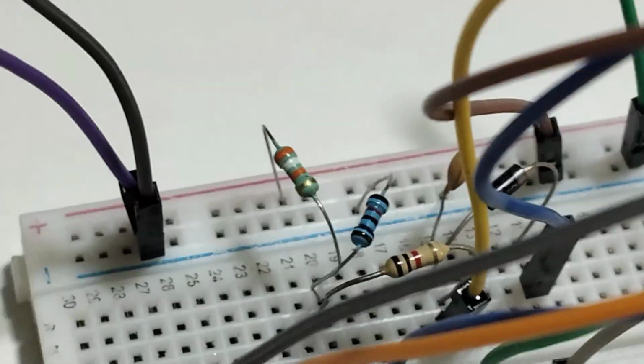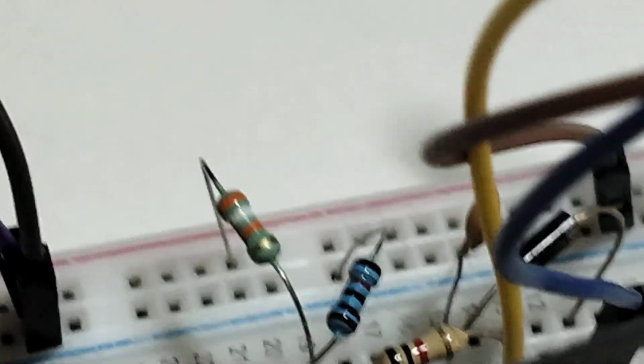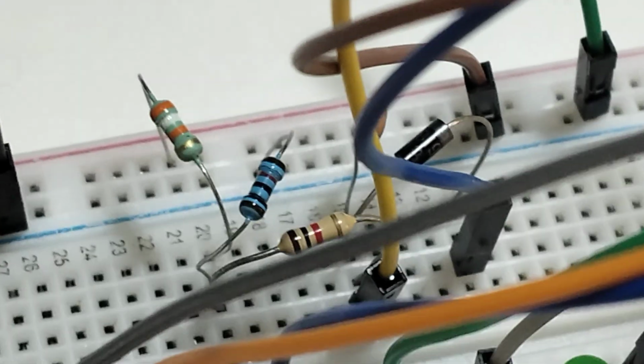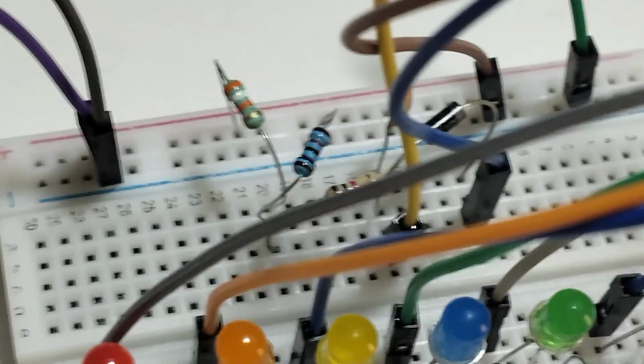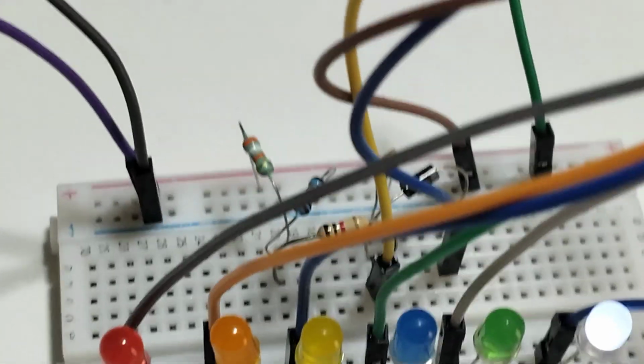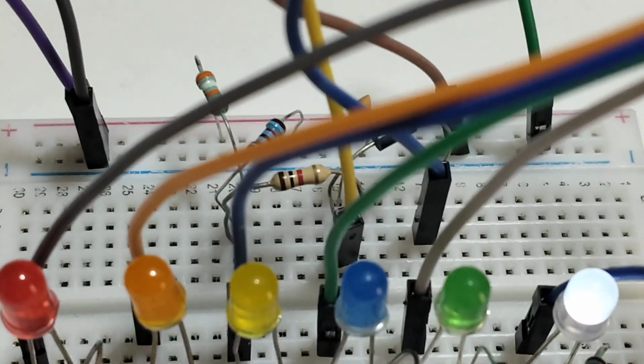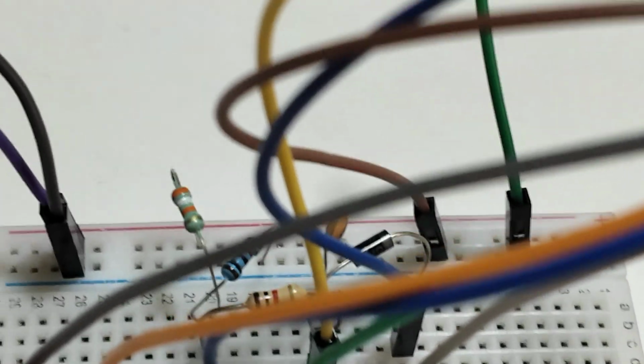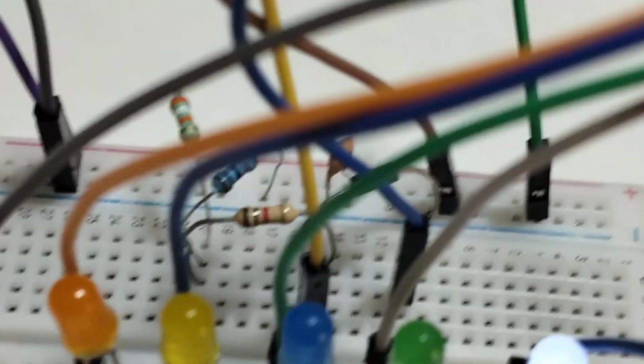So here I have a resistor divider of 39k and 10k, and we're going to be measuring across the 10k. By the voltage divider rule, it's going to get a smaller voltage. After that I just have a series 1k, which is not really needed, but just for overcurrent protection I have it there.